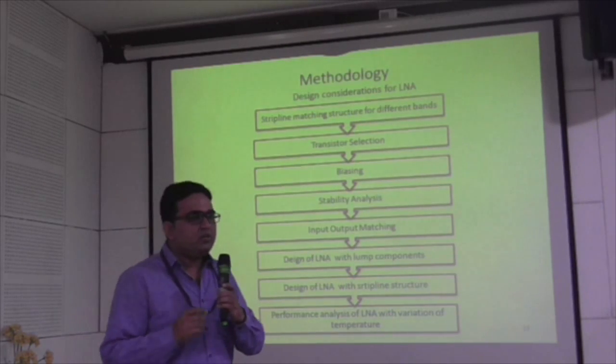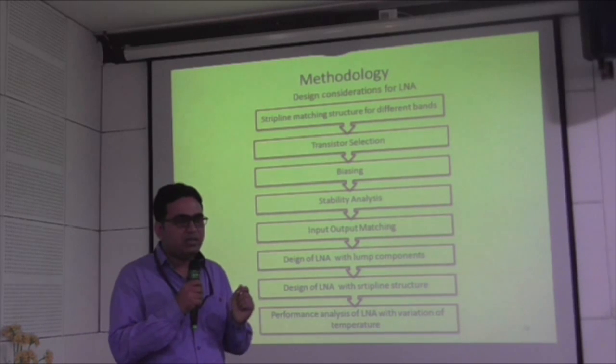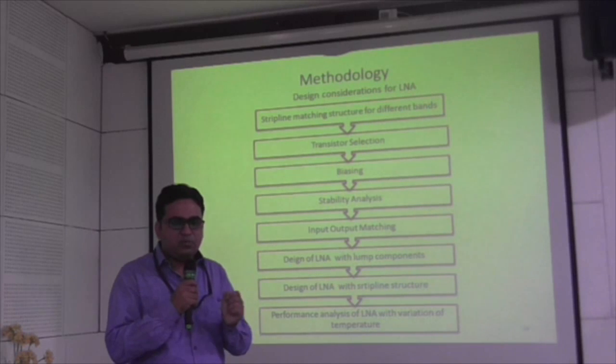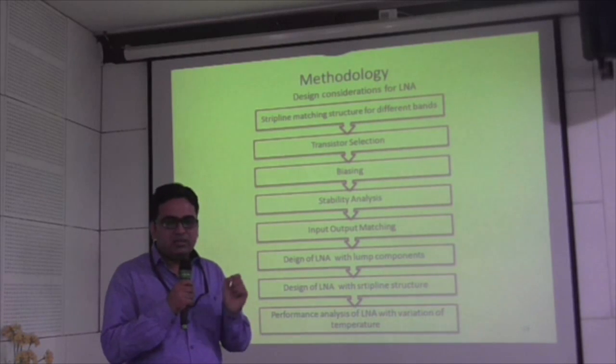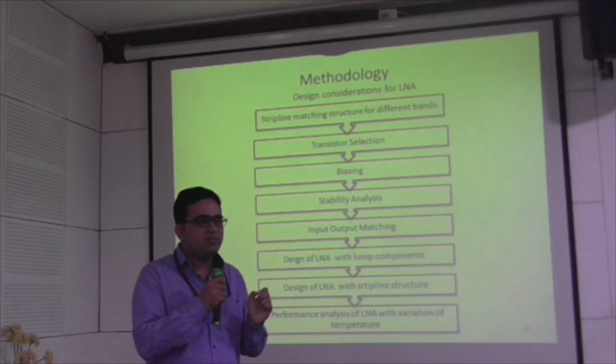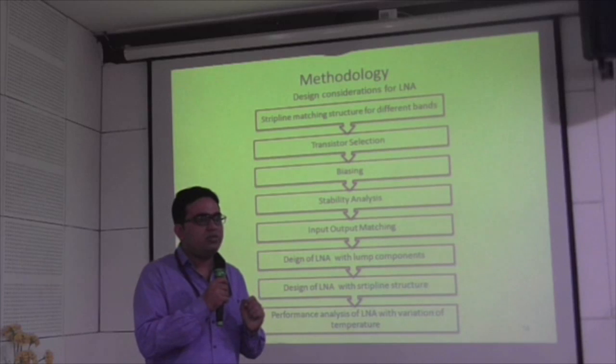So this is the methodology I have followed. First of all, I worked on the matching structure, the strip line matching structure. Then selection of the transistor, then selection of the biasing, then stability analysis, and input and output matching. Then design of the LNA with lumped components, then design of the LNA with strip line components, and then I did the performance analysis of the LNA.